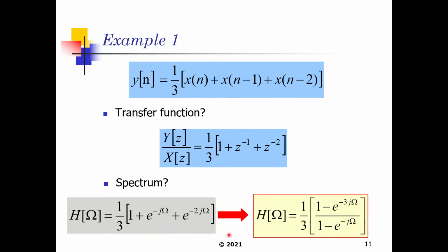So it's equivalent to shortcuts in the summation series by using either the arithmetic progression or geometric progression formulas in particular. I believe in this case it will be the arithmetic progression formula for the sum of a series. We get into that in a little bit as to how the frequency response would change depending on how many terms we have in the moving average filter.